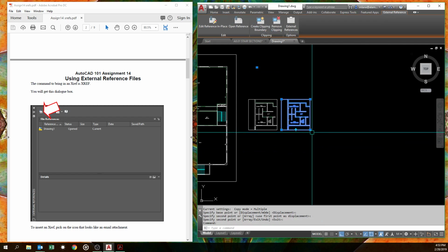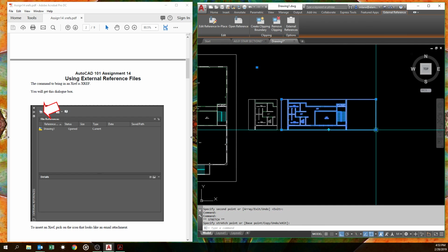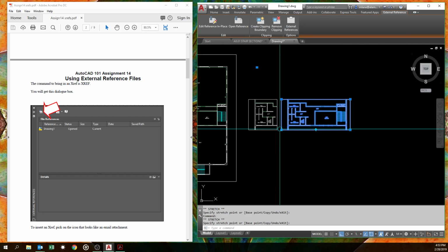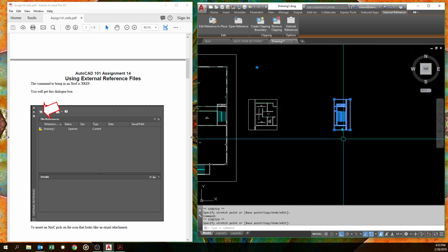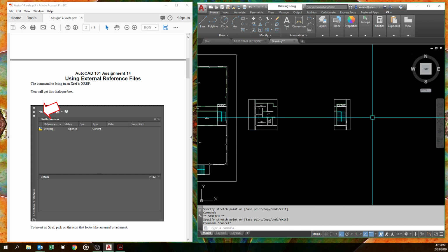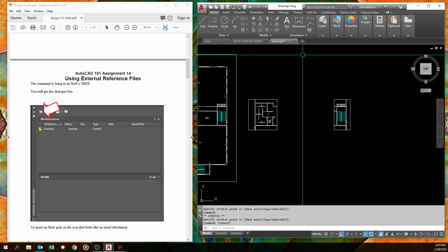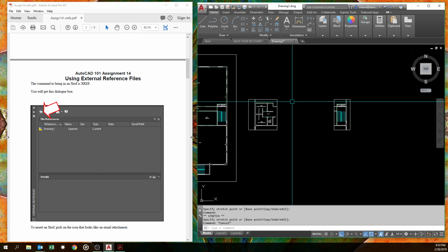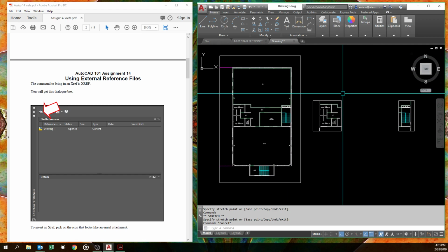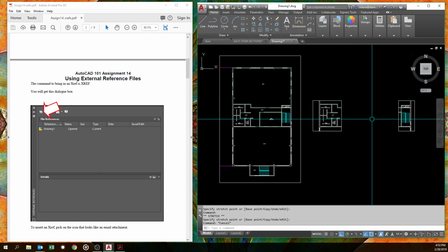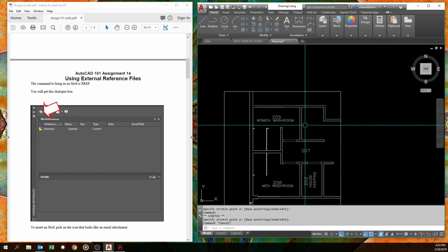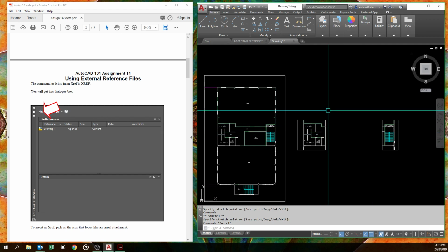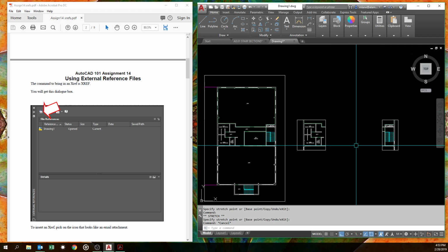And one thing about these, you can also drag the grips to edit them. So once you have one, you can just copy it and adjust it as you need it. This makes it very easy to do a lot of enlarged plans next to each other without having to do viewports and all this other stuff. We could start our dimensioning in here, and it's easier to do that in model space rather than in paper space.